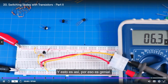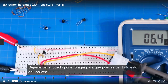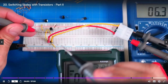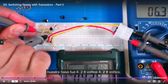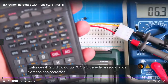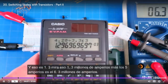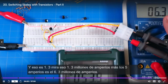And here, this is why this is cool. All right, so let's go with our other meter. Let me see, can I put it right here? So you can see this all at once. Let me see. Okay, so again, going into our base is 4.28 volts. All right, so let's do the math. So 4.28 divided by 3.3x10^3, right? V equals I times R, right? And that's 1.3, look at that, 1.3 milliamps plus the 5 milliamps is the 6.3 milliamps.